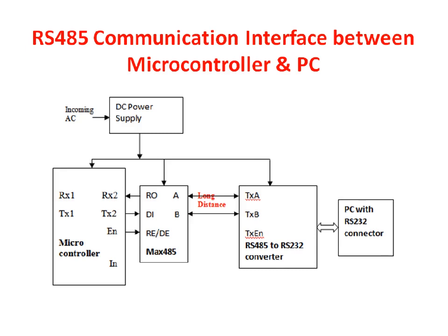are fed to the RS485 to RS232 converter before connecting to a PC, because generally PCs do not have an RS485 port, they only have an RS232 port. That's why the RS485 signal has to be converted to RS232 logic level before feeding it to a PC.